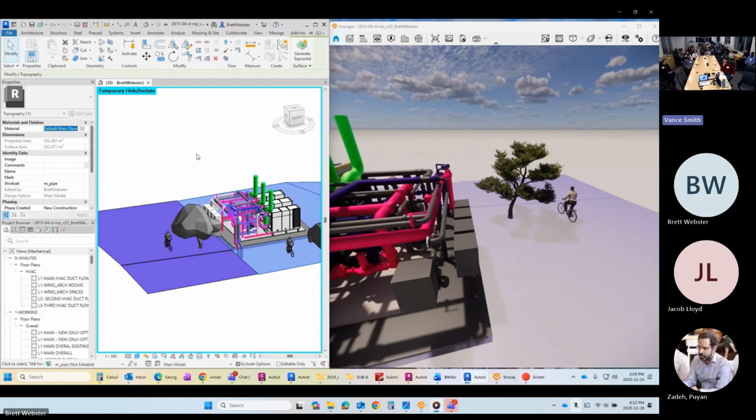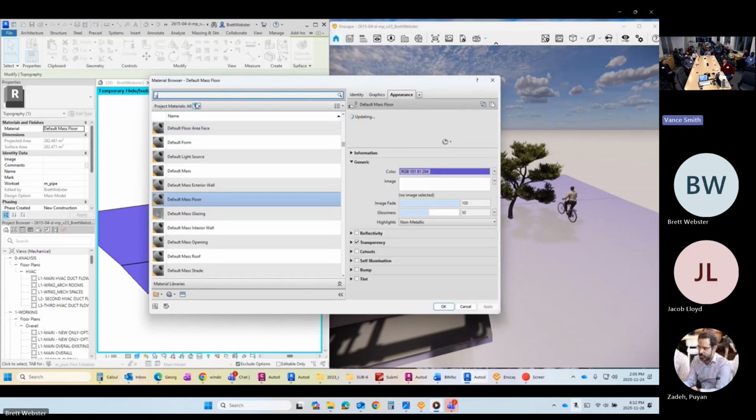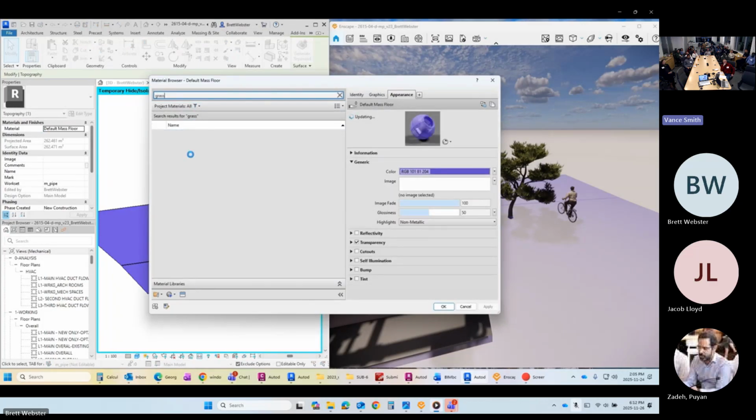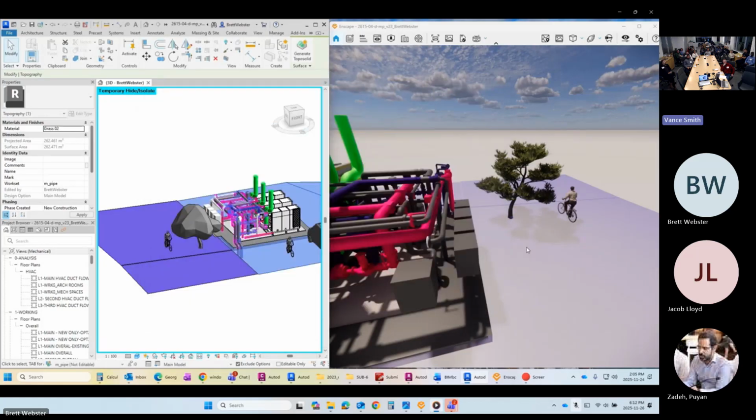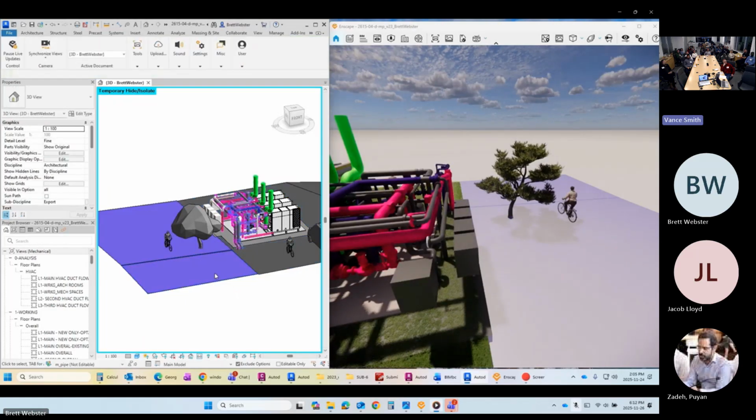we have to do all that through Revit. This is one of the issues with Enscape, I believe, is that it really needs the Revit link to apply those materials. So it's not fully standalone. You still have to have the link. So at the moment, we're just applying something like grass, and grass is one of these animated bespoke materials. So you'll see that in a minute.